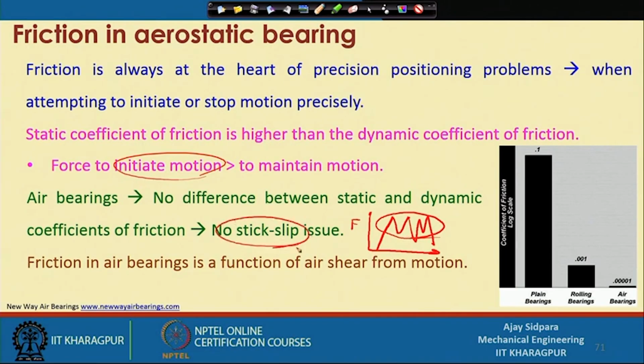So, this is called the stick and slip phenomenon, that mostly happens when you want to rotate something by hand. If you consider your carriage, when you want to penetrate your tool into the workpiece and you are moving by a wheel, right, you have a circular handle here and then you are moving this. At that time you will feel the stick slip phenomenon in the machining process, that is a very common issue.